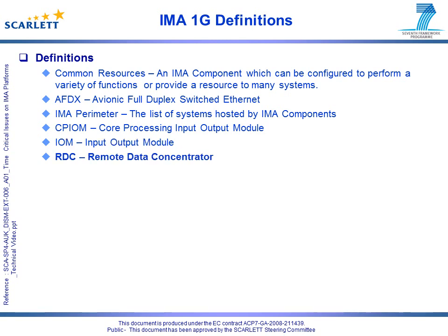RDC, Remote Data Concentrator. Within IMA 1G, the RDCs were system-specific, often without an AFDX interface, usually A429 or CAN, and connected to the CPIOM or a system-specific LRU.